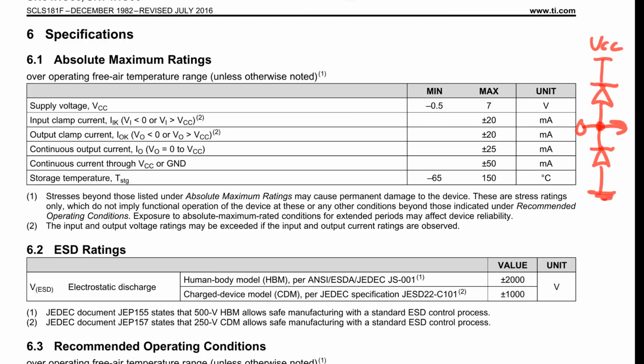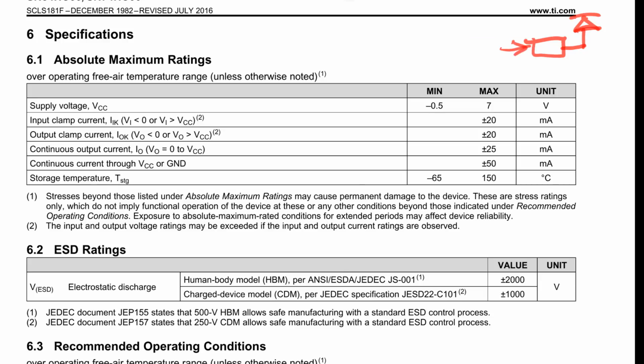So when this input here goes, say, plus 6 volts or whatever, that's bigger than VCC up here, which might be 5 volts, therefore current is going to conduct through the diode here, and that's what they're saying. You want an absolute maximum there of plus minus 20 milliamps. So anything over 20 milliamps and you risk actually blowing your input clamp diodes. So don't exceed that. So how do you avoid exceeding that? Well, I've erased my little diagram here, but if you know it's going to clamp, you have an input current limiting resistor like that. Depending on the maximum voltage, V max, that you have on the input, you choose that resistor value to limit the absolute current through that clamping diode to plus minus 20 milliamps. If you're looking to protect your device from overloads via this clamping mechanism, which you might if it's hooked up to any sort of external circuit, for example.